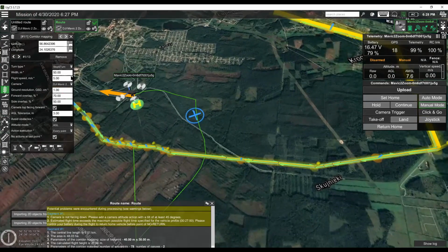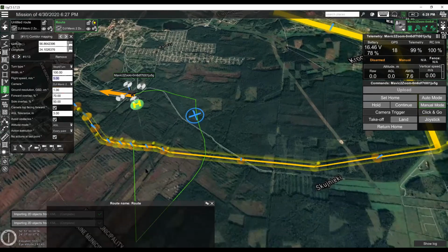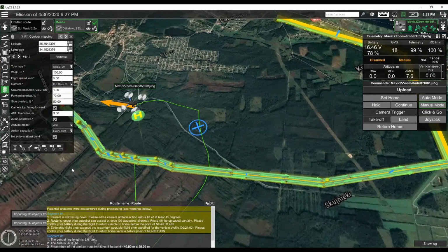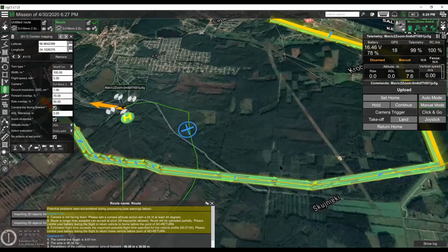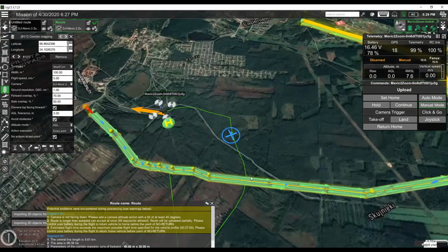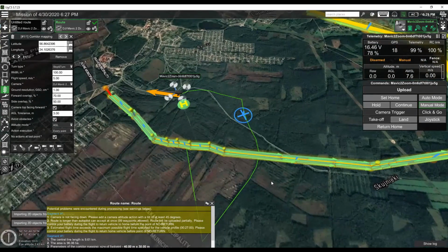If we set it wider, for example, 100 meters between the lines, there will be a flight path along the whole line till the end. Then the drone should return home, then go again, and complete this flight 4 times. Even with battery changing, it might be very difficult.